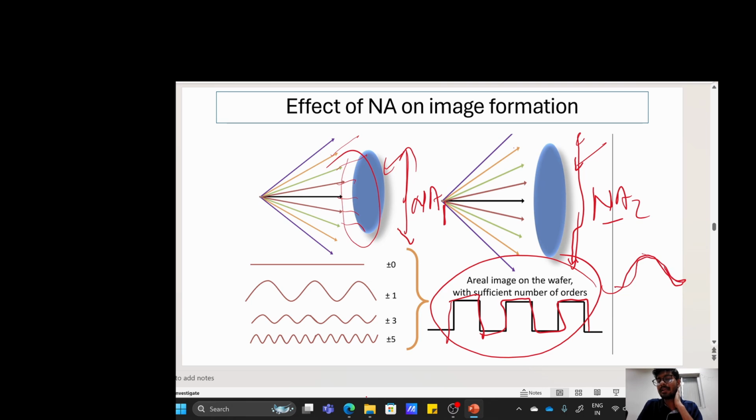This kind of energy profile of the light will be there. Because of that there will be some problem, because if you see it collectively with the contrast curve, that will give some kind of wedge function that will be replicated on your substrate, or on your photoresist.